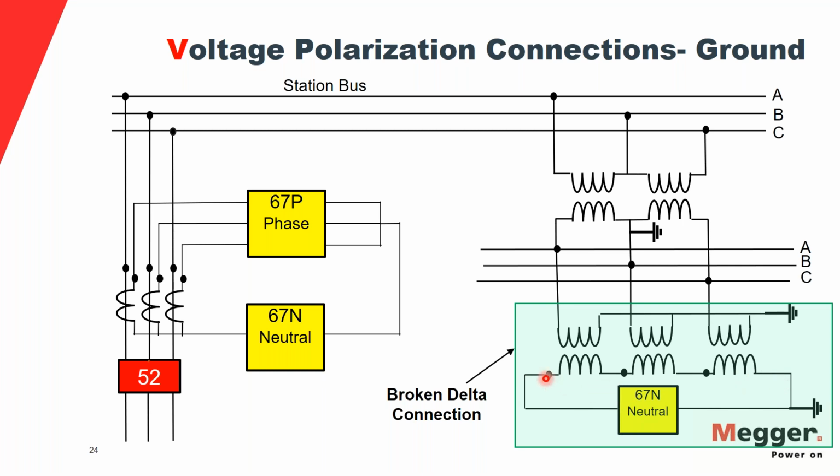When you do this, this point right here is computed from Kirchhoff's voltage law. It computes phase A voltage plus phase B voltage plus phase C voltage. If you remember the symmetrical component theory, phase A voltage plus phase B voltage plus phase C voltage is 3 times the zero sequence voltage, correct? So that's where we measure zero sequence voltage from in the world of electromechanical relays. Even microprocessor relays employ this concept, but we'll see that later.